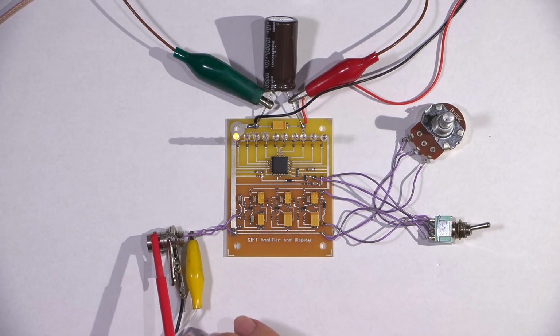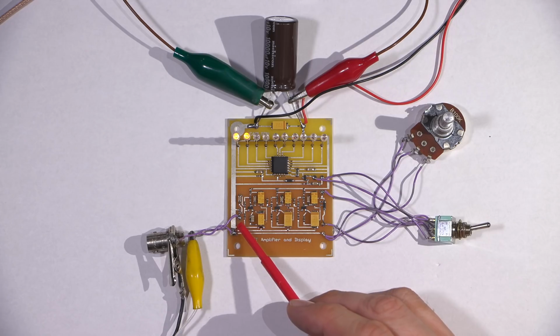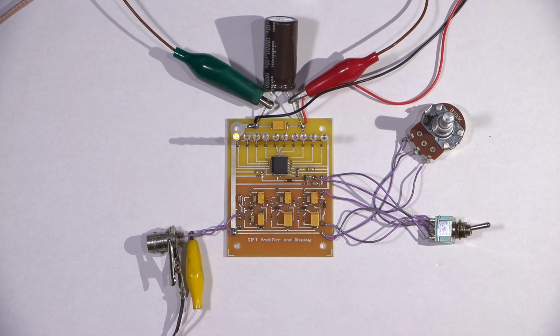If I was to attach this to an antenna, this display would just go right to the top and it would listen to just random noise and hum, right? So, in order to look at a signal that is going to be about, we'll say, 50 microvolts right now, we'll read it and get an exact signal here in a bit. In order to look at a signal that is 50 microvolts or so, standard oscilloscopes will not see that.